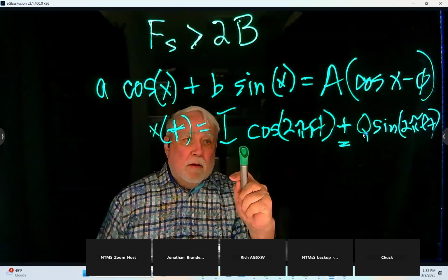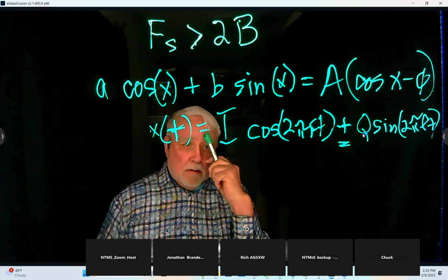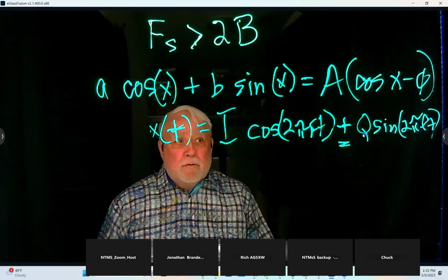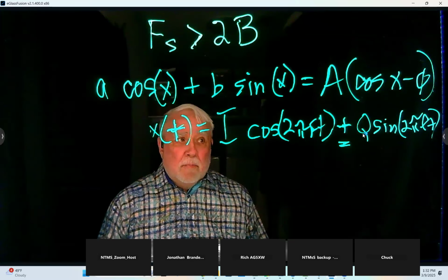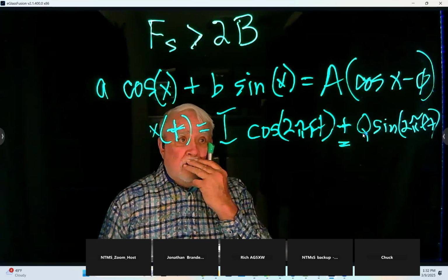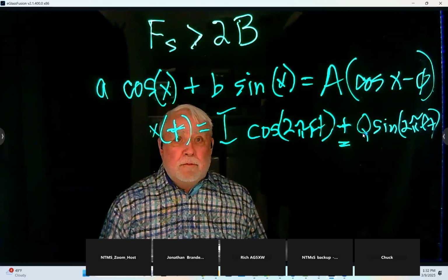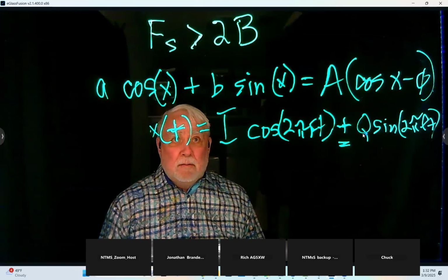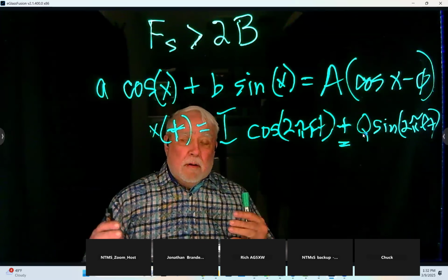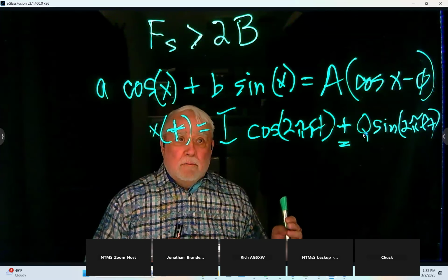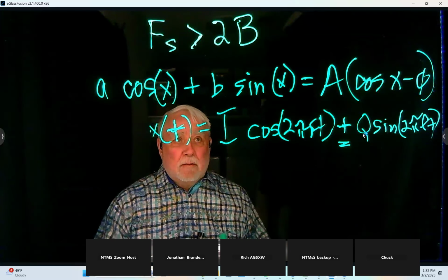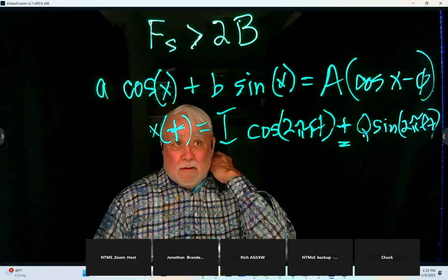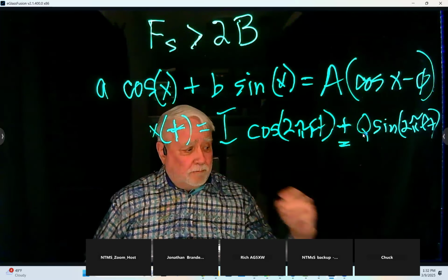Now, you can certainly multiply quadrature sample signals, and the math is completely different in terms of complexity, and we really need to have exponents to do that. But adding and subtracting is really all you have to do for simple forms of modulation to get a transmit signal. And so that's kind of where I want to start, is to carry this on through to the simplest of transmitters, not CW, but at least AM, and demonstrate how this math actually turns into a signal.